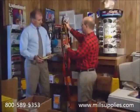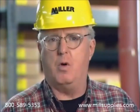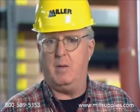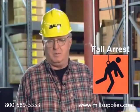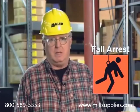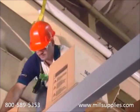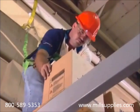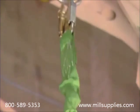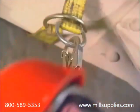It is up to the employer to select the safety equipment which is appropriate for a particular situation. Fall protection can be divided into 4 functional categories, which are identified by symbols. The first category is the personal fall arrest system. The system is intended to come into use only in the event of a fall. A personal fall arrest system consists of a full-body harness, a connecting device such as a shock-absorbing lanyard, an anchorage connector such as a cross-arm strap, and an anchor point capable of supporting 5,000 pounds per employee attached.